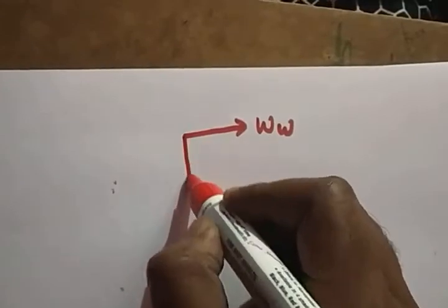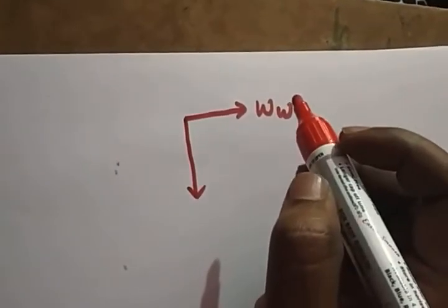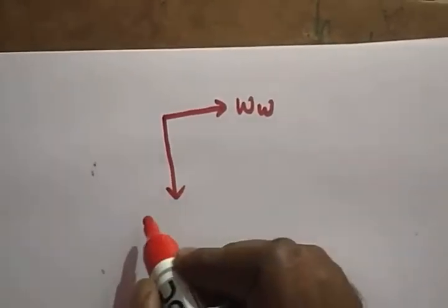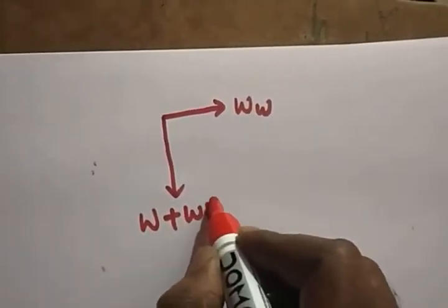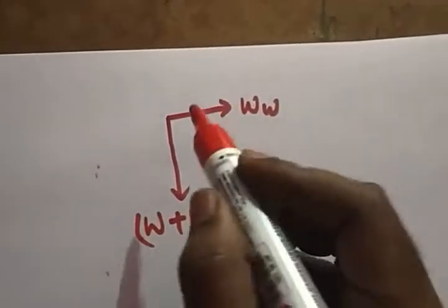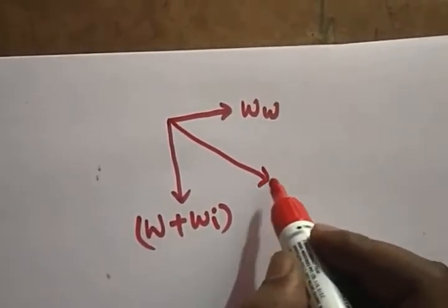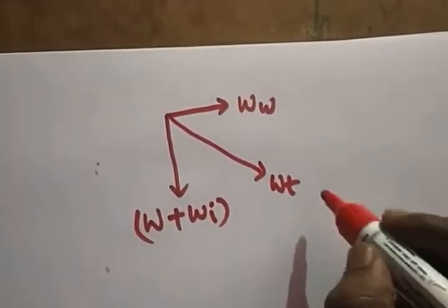So this is a wind force that is acting on the conductor, which is in the vertical direction, right? Always the wind force is in the vertical direction, and whatever force is acting on a conductor due to ice will be in a downwards direction, right? So what is that value? Weight of the conductor plus weight of the ice, right?